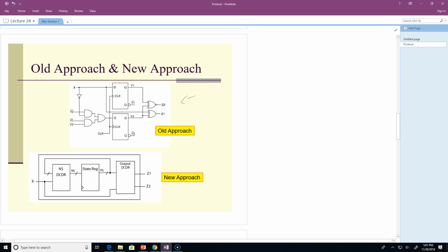Up here is just a typical simple state machine circuit as I used to draw them. We don't really draw them that way anymore, because generally speaking, this is considered the output decoder, this is the input decoder, and these are the state register. We've bumped that up to actual decoders, and we don't really look at this anymore. But it doesn't matter. Underneath the input decoder and the next state decoder, there's logic. Logic has propagation delays. Once again, this book doesn't really cover them that much. All devices have propagation delays. That means it takes a finite amount of time for that signal to go through the device.